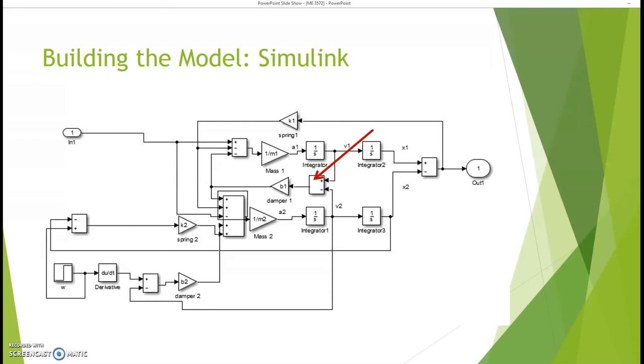The second spring and second damping forces are both dependent on the ground profile W, velocity 2 and position 2. These forces are acting solely on the suspension mass and will be positive forces inputted into sum 2. The controller force in 1 acts between the two masses and is attached to both sums.